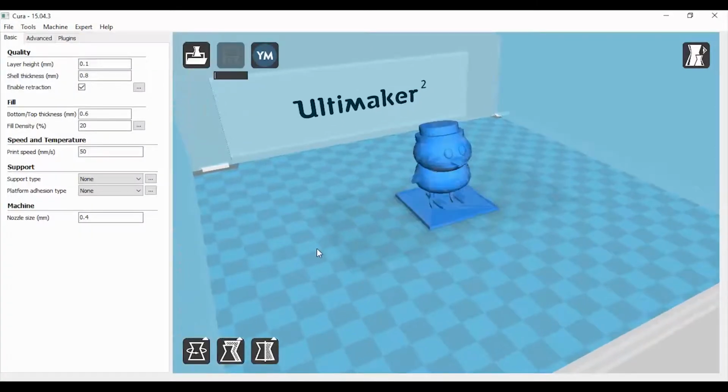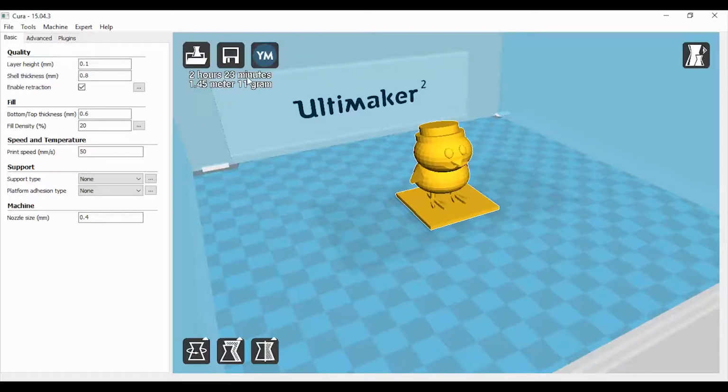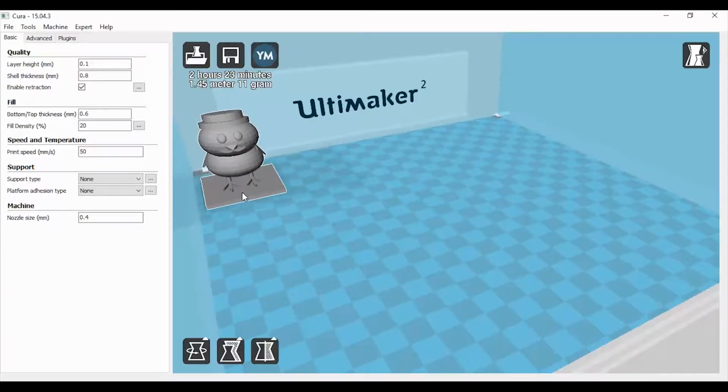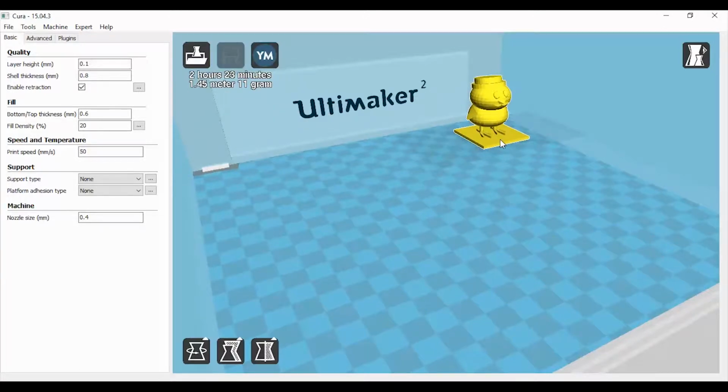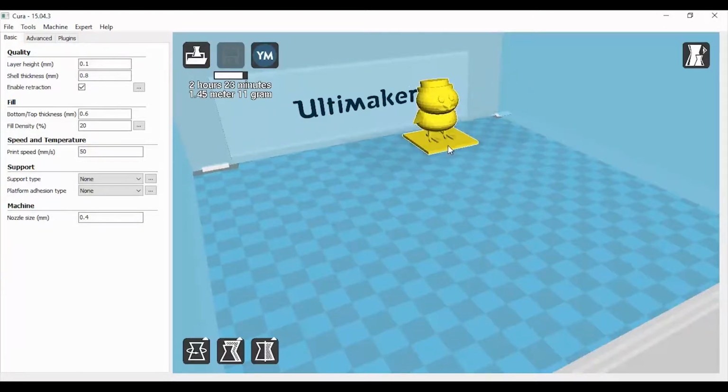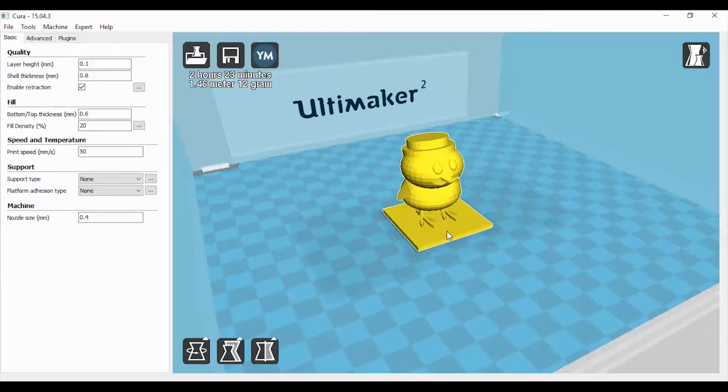We'll navigate to our file of interest, and you'll see it generate while loading the total print time estimation as well as the amount of material and the mass of material. Now we're able to drag our part around the virtual print tray by clicking and holding with the left mouse, and when the part turns gray it's off stage, yellow is on stage. You can see all the while the print time and estimation of material updates.